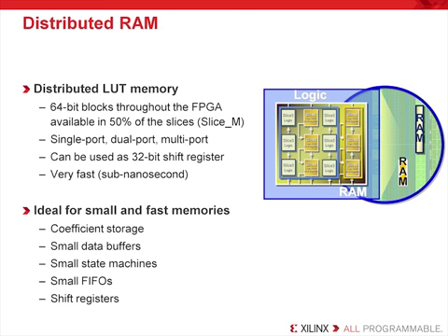Distributed RAM is another functionality of the lookup table. Each LUT can be reprogrammed to implement a tiny 64-bit RAM. While most customers do not use this resource, many DSP designers do, so it's a good feature to be aware of. Many DSP designers will use the Xilinx system generator to build their DSP functionality.